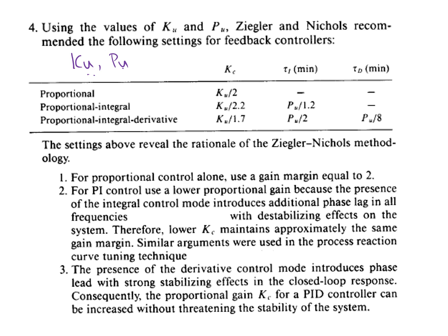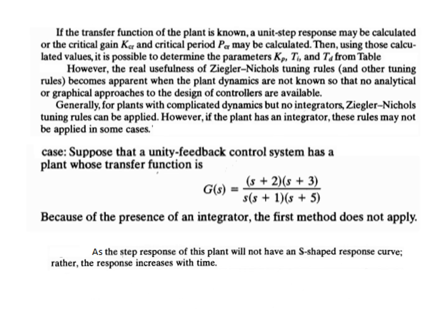So how do I do that? First, start with a simple proportional controller and keep on increasing or decreasing until you get sustained oscillation. And the value for which you get sustained oscillation is called Ku. And then the time between these two peaks is called Pu. Then substitute directly to get the values. Okay. So we'll check this problem.